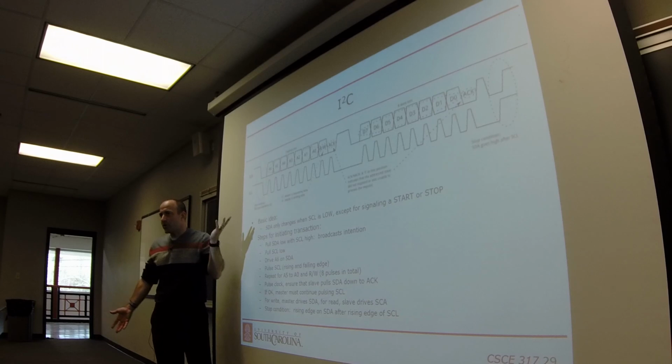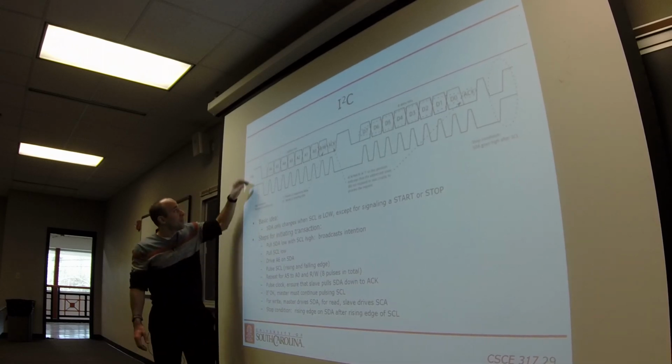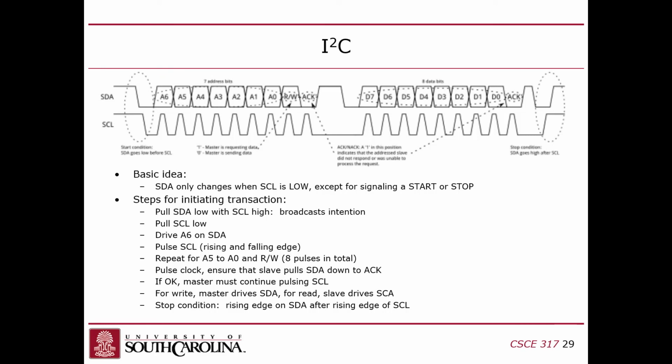So what's the significance of that? Well, if you violate that rule and you change the data while the clock is high, which happens right here, see, the clock is high and the data drops, right? That means something special. That means start. That's a start signal, right?